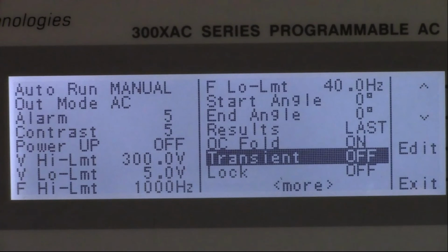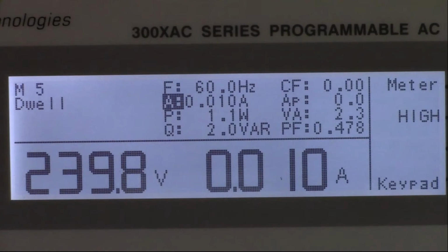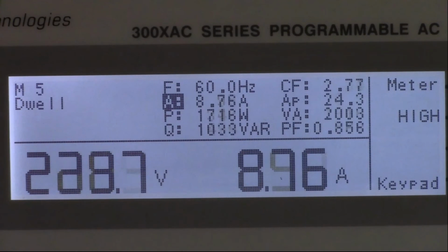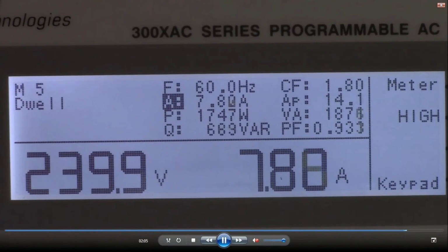In doing so, this allows us to run this vacuum motor successfully past the inrush stage. You can see here that we're applying 240 volts. Then when the motor turns on, it draws 19 amps. I saw 19 amps come up there for a few seconds. The voltage was dipping. And then what we saw additionally is that now it's at a steady state. So this power supply could meet the requirements for steady state, but was not able to meet the inrush requirement. Having OC fallback allowed it to power up this vacuum motor successfully.